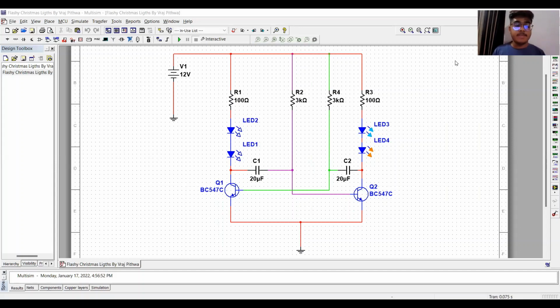Meanwhile, the current is still flowing through the resistor. This causes the capacitor to charge up again, and the voltage will rise towards a positive level until at some point it reaches 0.7 volt. This causes the other transistor to become active, closing at that side. So at this point the base reaches 0.7 volt, the transistor becomes active, the LED lights up, and the voltage at the collector drops to zero voltage.